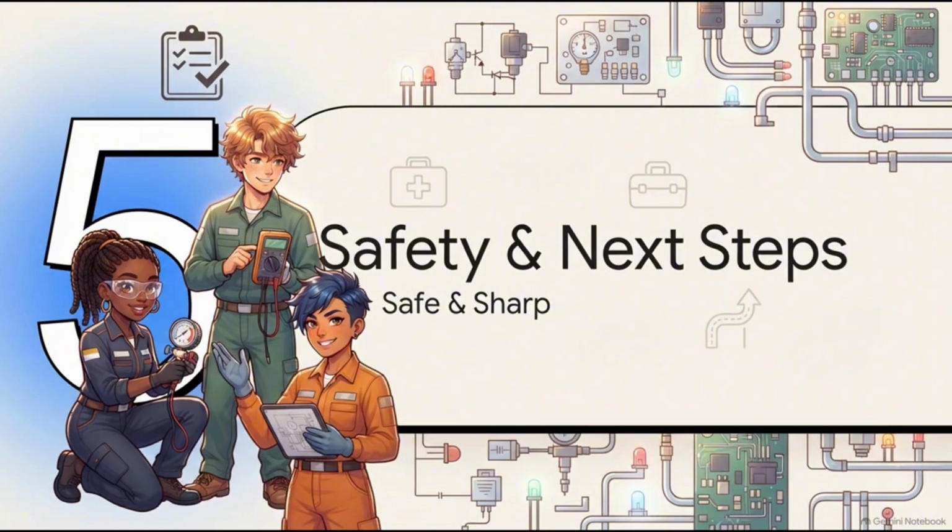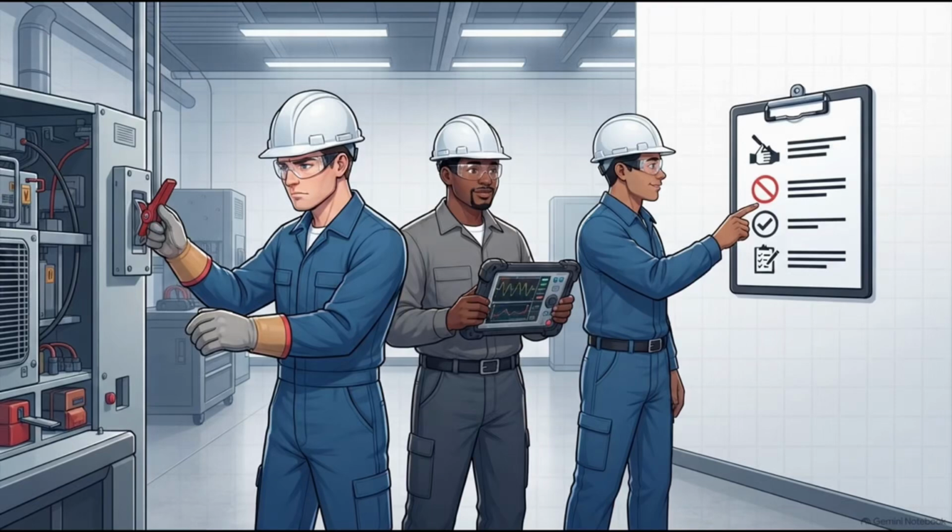All right, final section, Section 5, Safety First and Next Steps. There are some strict non-negotiables when we're dealing with safeties. First, always follow the manufacturer procedures. Next, always disconnect power when appropriate to protect yourself from an arc flash or lethal shock. And absolutely never permanently bypass a safety switch.